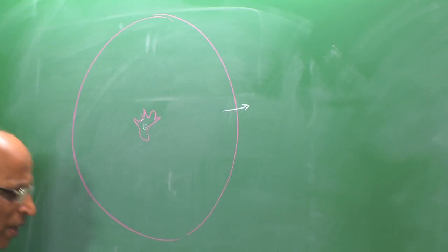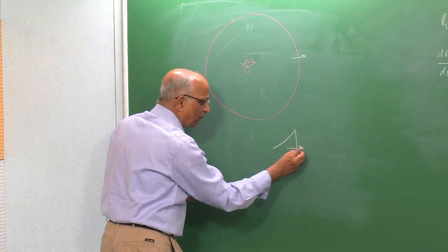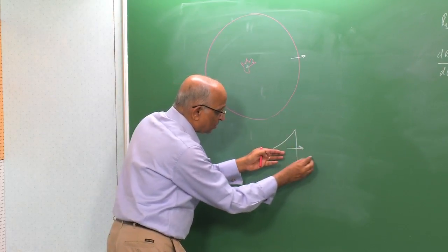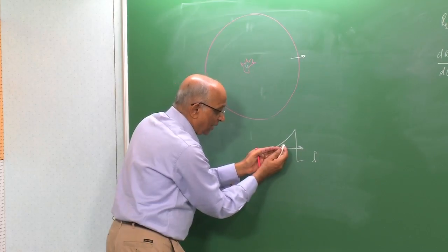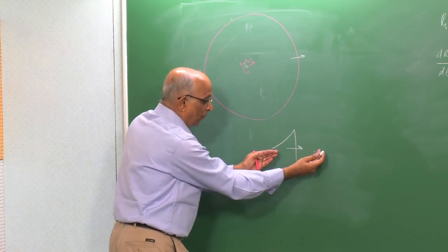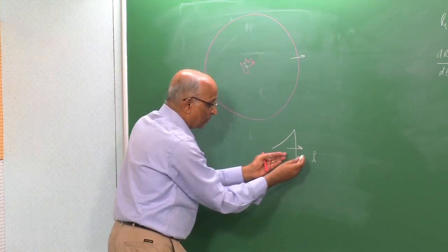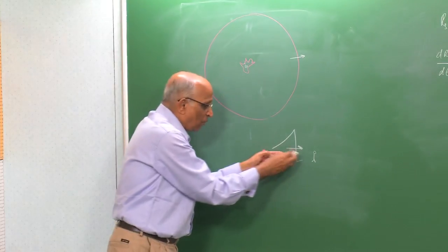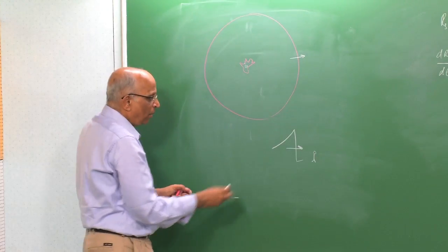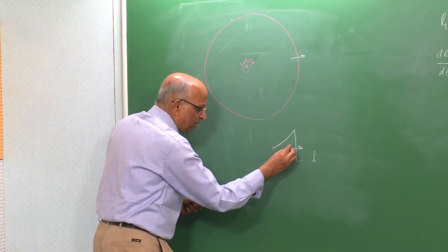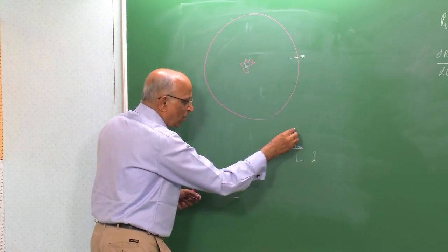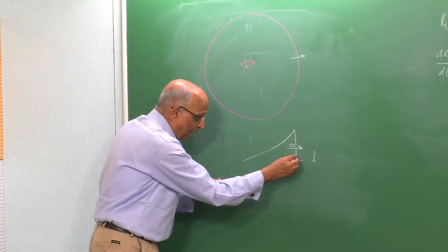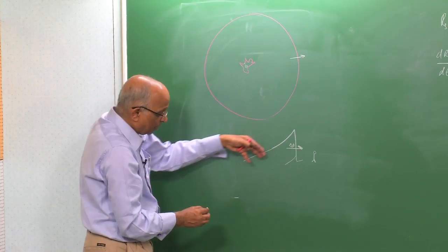We would like to know, when I have a wave like this coming, what is the overpressure, the pressure with which, supposing somebody is standing here, he gets hit by the wave. That is, there is suddenly a compression which really squeezes him. That means there is an overpressure which affects him, and in addition to the pressure rise delta P, there is also, behind it, a pressure fall. We saw this, we found that an N wave is like this, the pressure keeps falling.